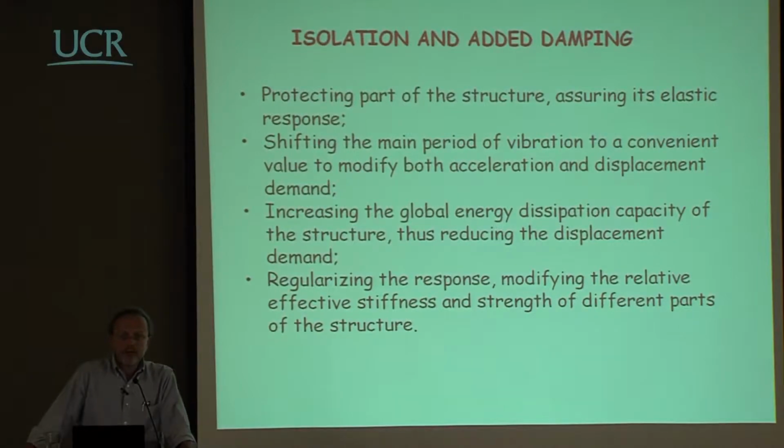This can also be obtained through something which is not exactly base isolation, but for example added damping, which is in a general sense considered to be in the general area of isolation, and which implies that you are reducing the displacement demand, as we have been discussing today, and therefore you are reducing the action.